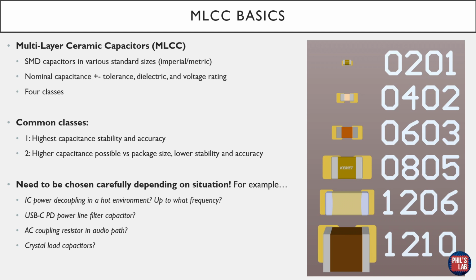Multi-layer ceramic capacitors, MLCCs, you will find on pretty much any PCB, whether that's for power decoupling, filtering, bypassing, or for example timing circuitry. They'll be used anywhere. We'll only be talking about SMD capacitors in this video, and these come in various standard sizes. You'll have seen imperial and metric, which can be quite confusing because imperial sizes such as 0201 also exist in metric as 0201.